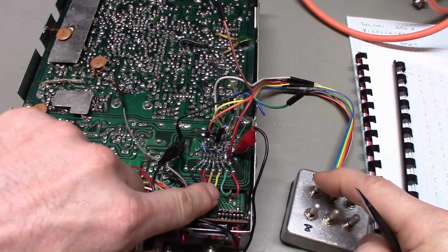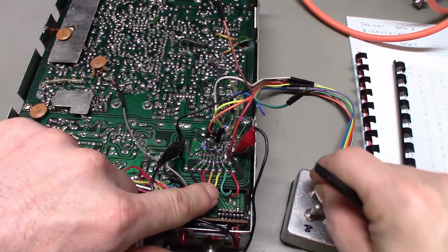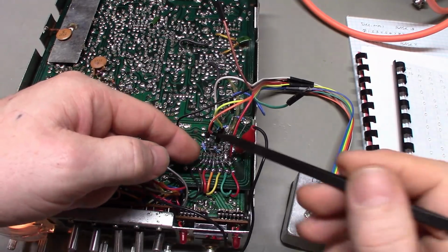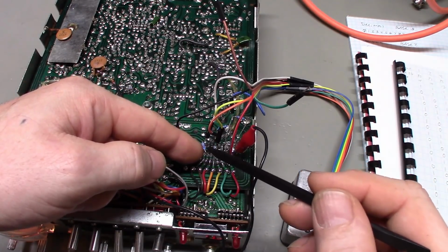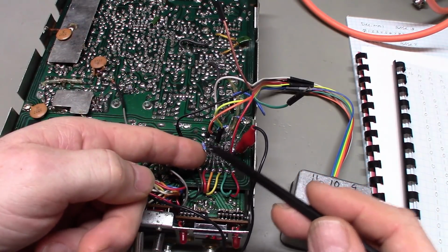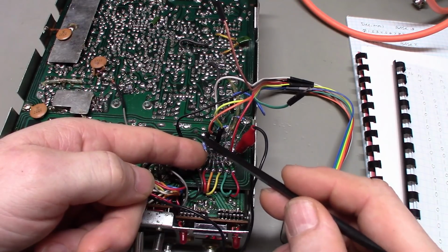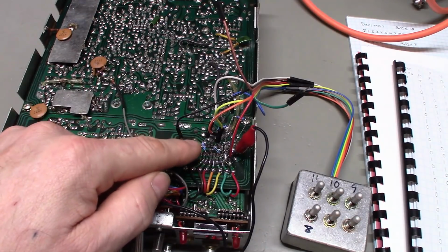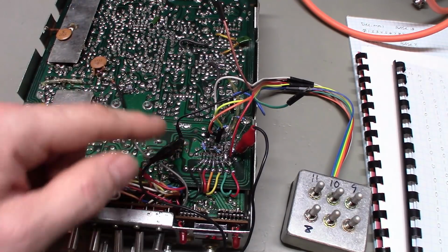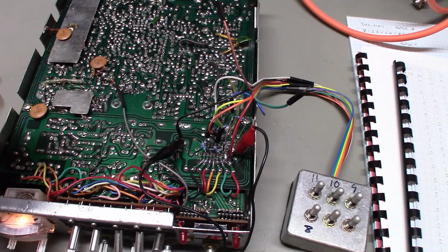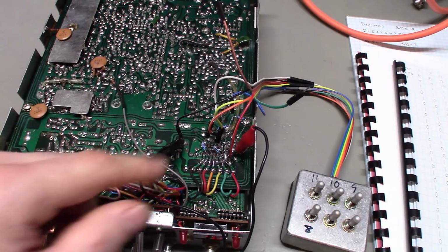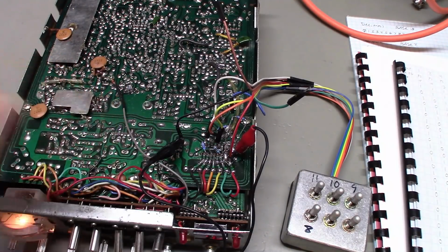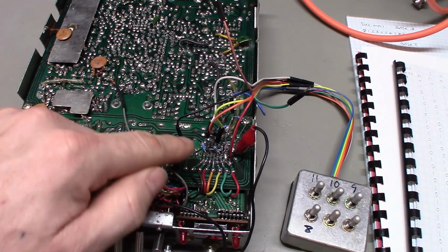Now, if you have voltage present here and you ground the pin, you're grounding it on the other side of the resistor. You are going to burn up a little bit of electricity in the form of heat through that resistor, because you've got ground potential on this side now and voltage source on this side, but you've got a fairly high resistance value in there. In this case, I've got 3.3K, or 3,300 ohm resistors in there. And these don't even get to the point where you can feel they're hot. There's so little power being used. But that's how that's done.